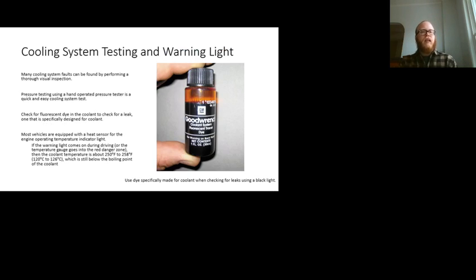If we have a leak, lots of techs like to use dye because it can help you more quickly see little leaks. Usually we go through and clean off any residual coolant. Then you put the dye in the system and let it run. Definitely let the vehicle come up to temperature, and with a black light and those special yellow glasses, you go around and look.